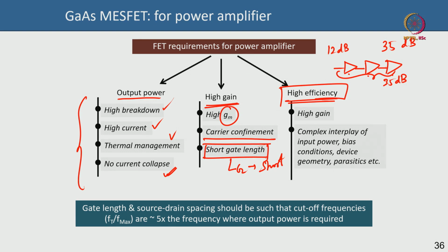Because the power amplifier boosts the power and sends it through the antenna to the nearest base station or cell phone tower. So, on the transmission chain, you have the power amplifier to amplify the signal from your cell phone and send it to the nearest base station. So, the power amplifier has to consume the maximum energy. The efficiency will directly determine how long your battery lasts. Because you cannot arbitrarily keep increasing the battery size and battery capacity, because a cell phone will become larger and bulkier, that is not what you want. So, an efficient power amplifier helps you increase the lifetime of the battery.